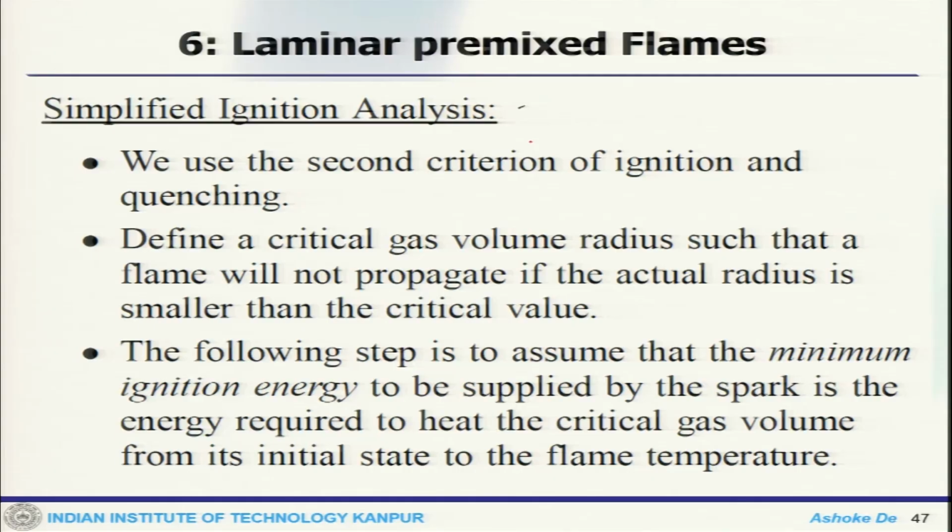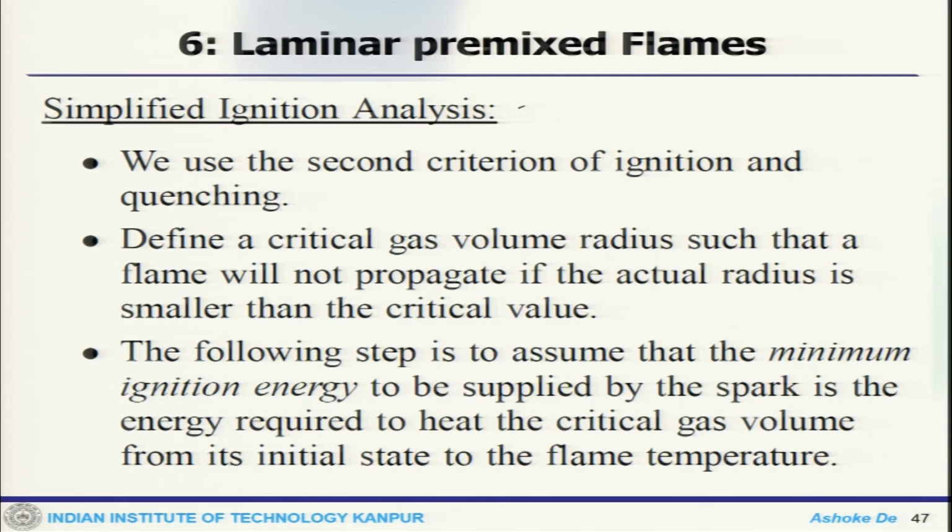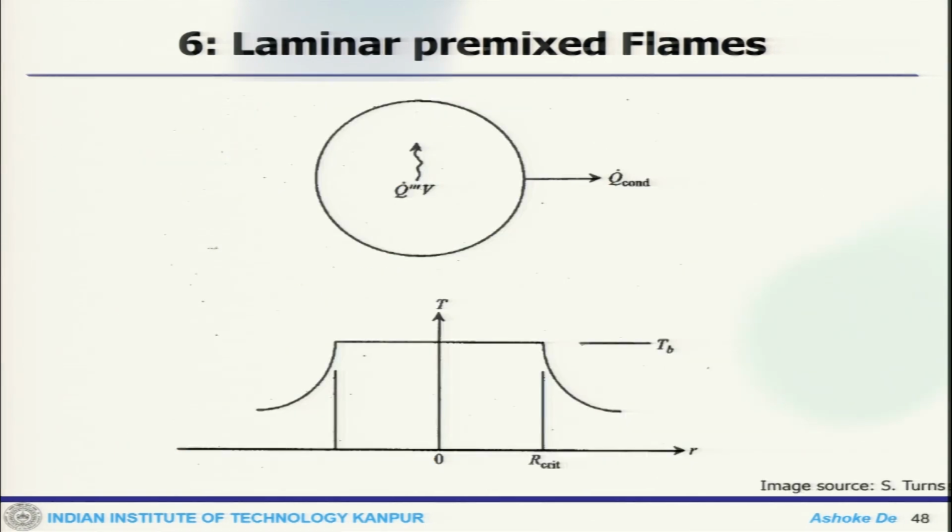Welcome back, and let's continue the discussion of the ignition analysis of premixed flame. We are doing some simplified ignition analysis, which we already discussed. What we want to look at is the minimum ignition energy, its application area, and the analysis. Basically, we will define a gas radius and then use the spark to find that out. So, this is the gas volume radius,